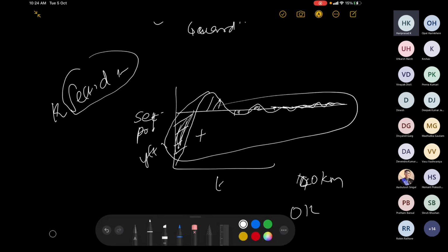So you would press it, and initially you would go up, and sometimes you might have pressed so high that the speed went more than 140 km/h, then comes down. Eventually the overall summation of the error would be very close to zero, could be close to zero, but never be zero.